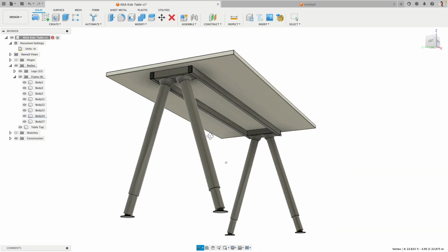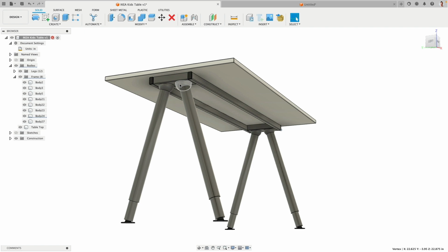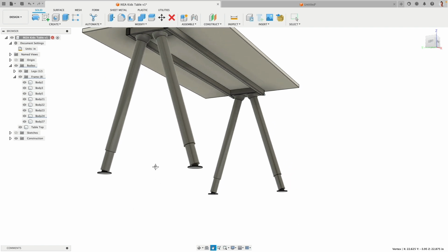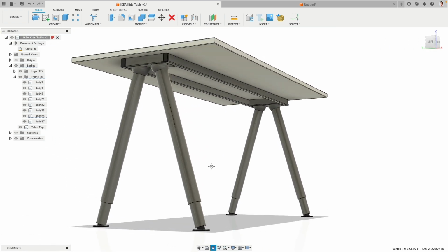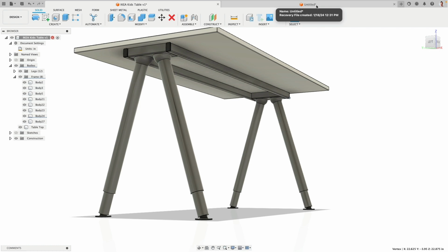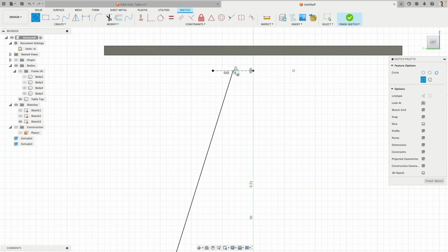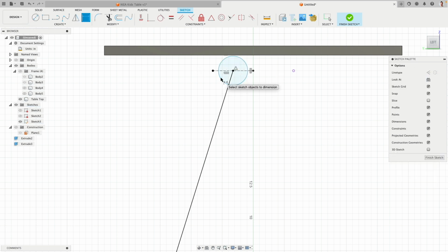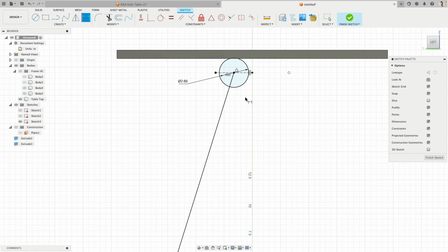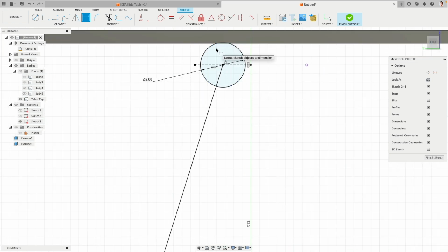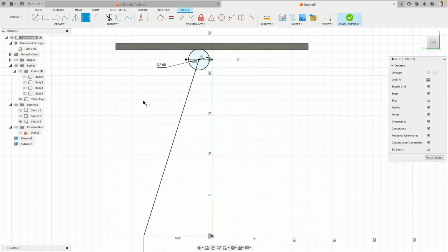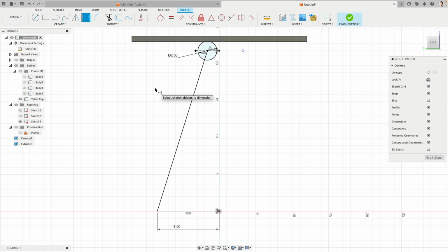So if I go back to the finished CAD model, you see there is a spherical body, two telescope cylinders, and then we have the feet at the bottom. Okay, so go ahead. We will create a circle right here. I press D for the dimension, and this is 2.6 inches. Okay, very good. This is much bigger than what we need. We later only need 1/4. Yeah, we'll come to that later. But this is the socket where the first telescoping tube goes onto.